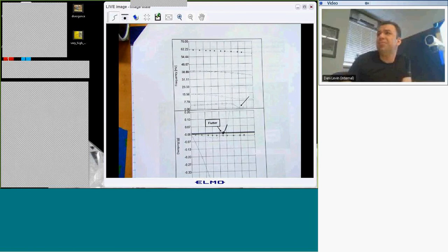Yeah, I have one question. When you did the structural analysis in ANSYS, did you consider the pressure forces acting on the wing, which is causing the softening of the wing and hence the frequency is decreasing? No, the answer is no.